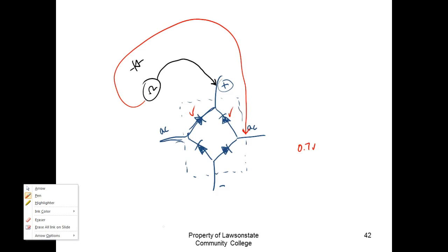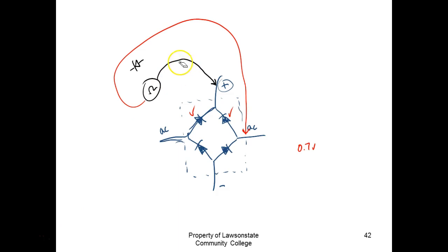What should we measure if we reverse bias? On most meters, it's going to measure overload. Y'all understand that? If you're not touching the leads with your fingers. So it's up to you what you want to do, but what I would do now is I would shift it around, and I would come over here, and I would take my black lead,